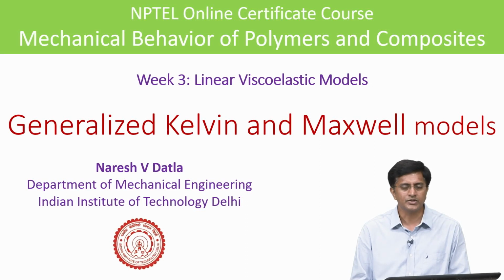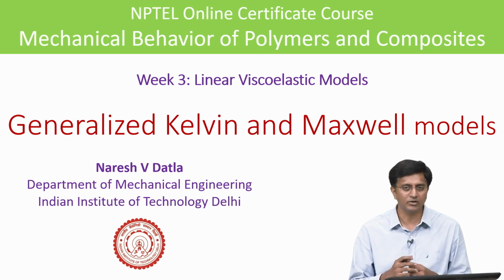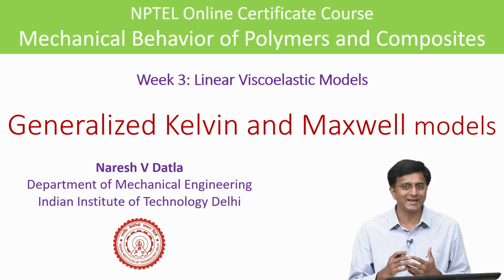Hello. In this video, we will be looking at the generalized Maxwell and Kelvin models. We need to recall that the Kelvin and Maxwell models we discussed are now the building blocks for us to develop these generalized Maxwell and Kelvin models, because these can be used to model a real polymer. A real polymer has several relaxation times or retardation times, which cannot be captured by a simple one Maxwell model or a one Kelvin model.